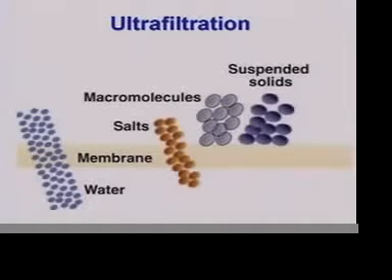Ultrafiltration is basically a larger sized microfiltration membrane, a larger pored MF membrane. And that, as you can see here, the water goes through, salts will go through, but both macromolecules and suspended solids are held back. So both microfiltration and ultrafiltration are based on pore sizes.